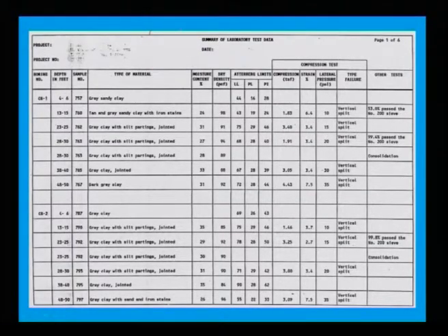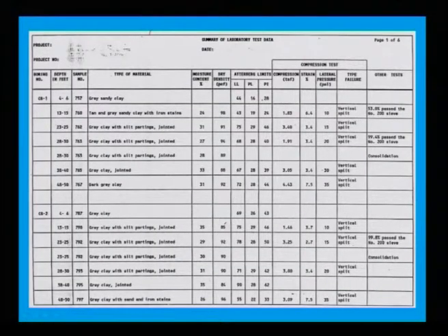So at every step this density has been recorded. If you look here, density has been mentioned. This is detailed laboratory data. Once density is mentioned, you go for sieve analysis data, classification data, as well as Atterberg limits. Atterberg limits are for fine grained soil classification. If you look here, liquid limit, plastic limit, plasticity index, everything, write it. Liquid limit you calculate from the laboratory, plastic limit you find out, and then the plasticity index.